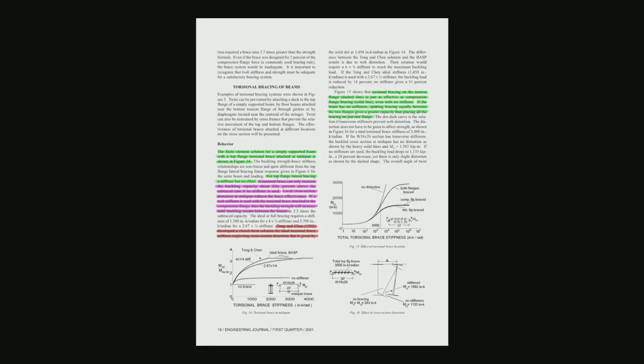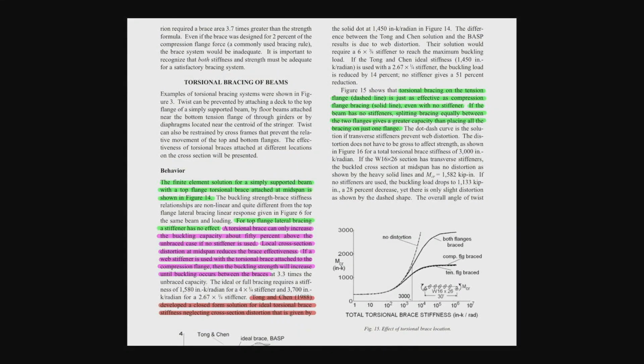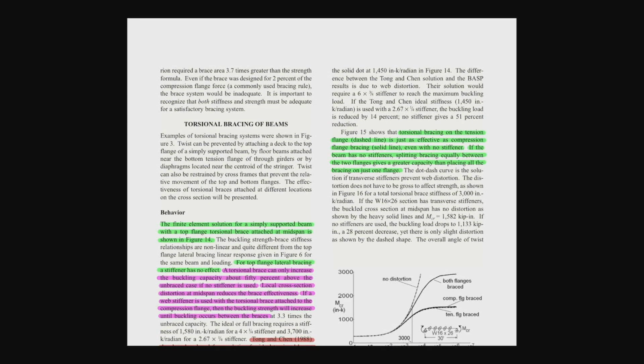and to here. So we finish up the matters about the lateral bracing of the beam, and another mode is the torsional bracing. And again, the code also already said so, and I want to emphasize: the beam and the truss actually are the same thing for my eyes. In the beam, the flanges are the top and bottom chords, right? The web is the diagonal chords in the truss, and that's it.